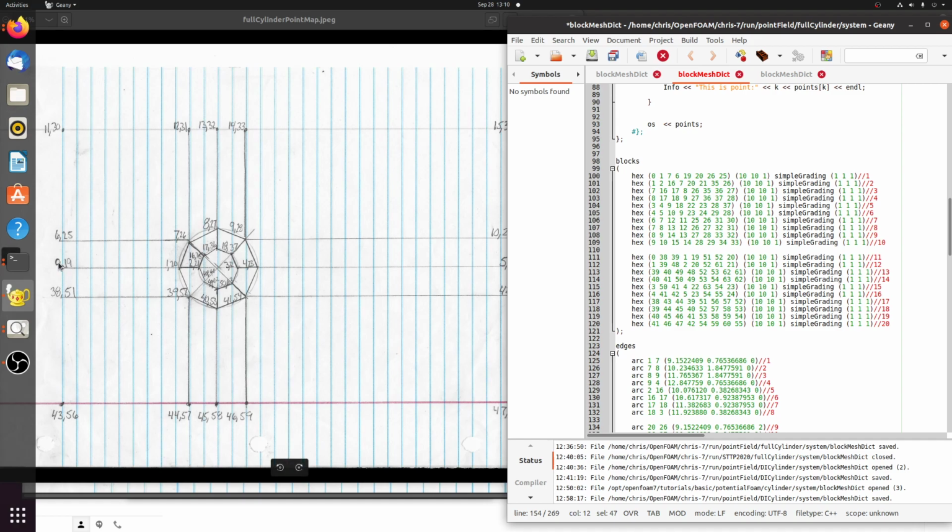Right now this is back. Remember, left is back. If I lifted the paper forward to us, 0 would stay in the back, and however far I lift it would be the z direction. You're supposed to take that whole two-dimensional quantity, flip it, and put the origin closest to your eye, and then go clockwise in the direction of the points for the blocks, to specify in the hex notation in the blockMesh dictionary.